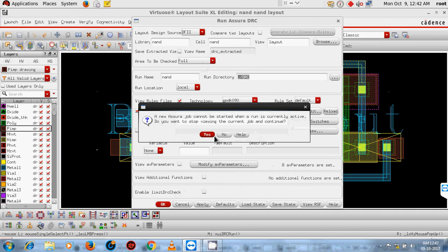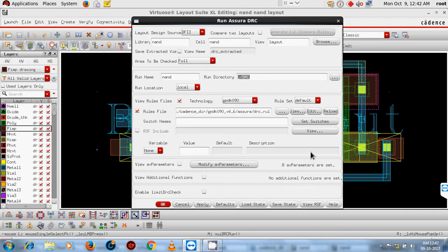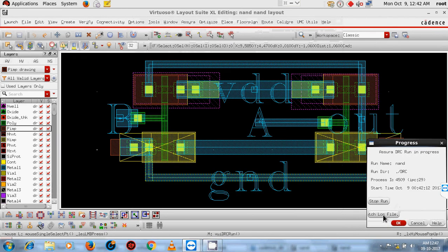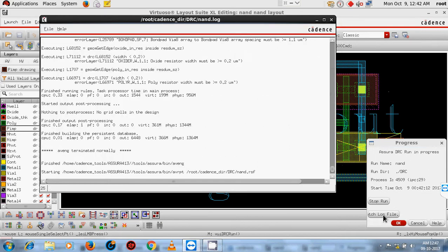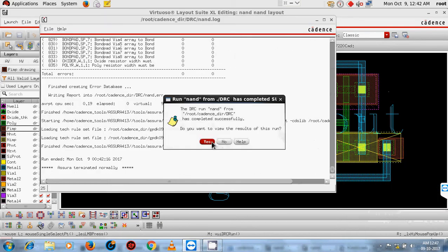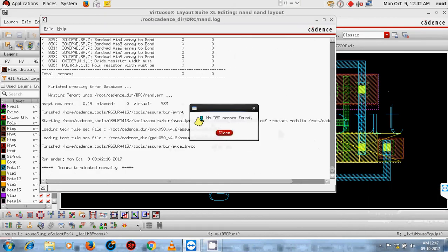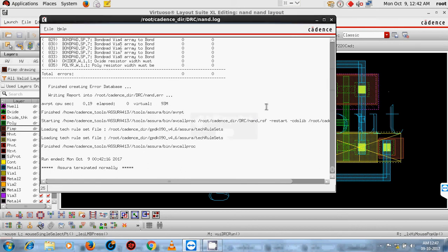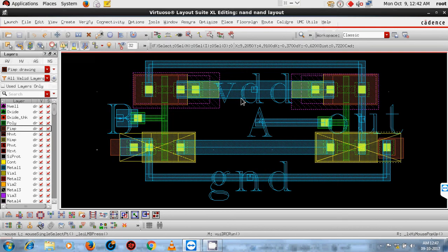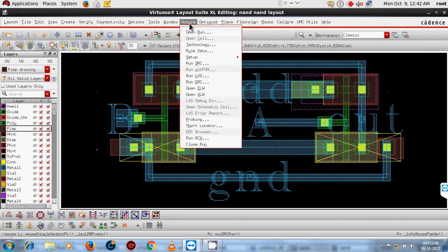Actually this is Cadence GPDK, and previously I was using SCL, so there is a little bit of difference between their bulk and layout. So there is no DRC error. Now move to LVS. So this is DRC clean. Okay, I know this circuit is small, but why is it showing error? Just due to the bulk of this device. So now move to LVS.